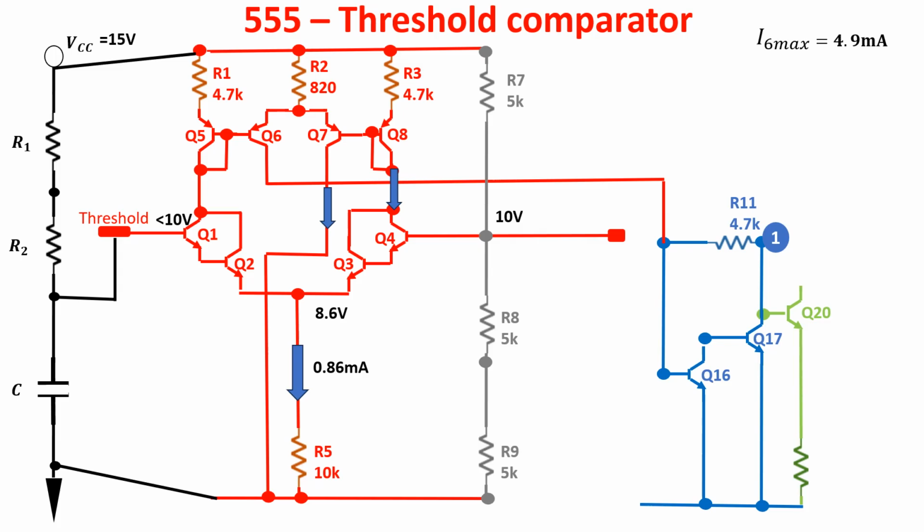The differential pair is not well balanced, so there is an offset of around 30 mV. But considering the voltage swing, this is not a big problem. According to the datasheet, the base current has a typical value of 0.1 microamps and a maximum value of 0.25 microamps. This means a Darlington beta between 3400 and 8600.